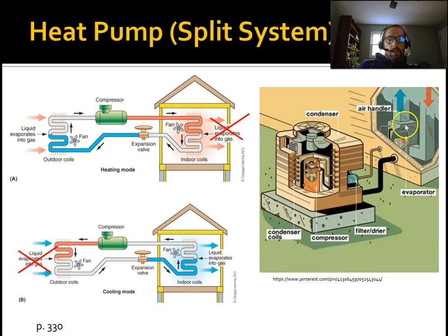And there's coils inside of this unit in here, and these coils, again, when you're in cooling mode, this is your evaporator, right? So it's evaporating the liquid, pulling heat from the air around it, from the air that's flowing through this return duct, and then it's flowing out. The cold air is blowing out, and then comes out here and dumps that heat outside.